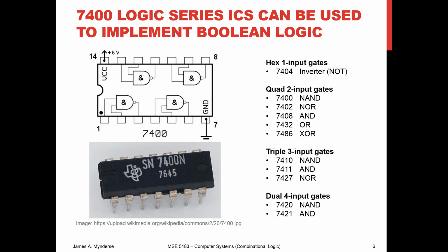But if you want to do these sorts of logical operations in hardware, and you want to do it at the 0 to 5 volt level, TTL voltage levels, then we'll use the 7400 series ICs. This is a relatively old series. They're a standardized sort of thing, so you can get them from different manufacturers, and they have standardized part numbers. So for instance, a 7404 is going to be a collection of inverters. There are going to be several inverters in one single dual inline package, or surface mount, I suppose, but we're going to use the dual inline packages because it's convenient for your breadboards.